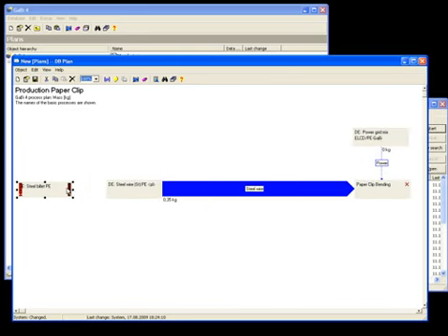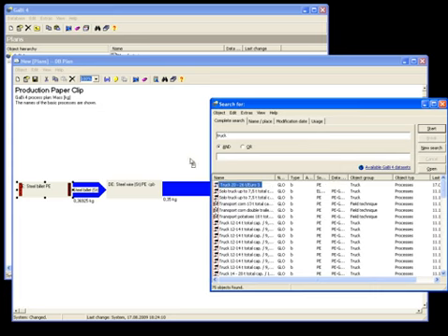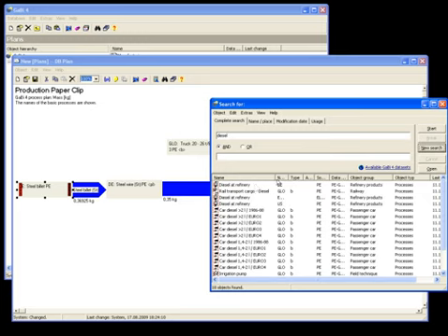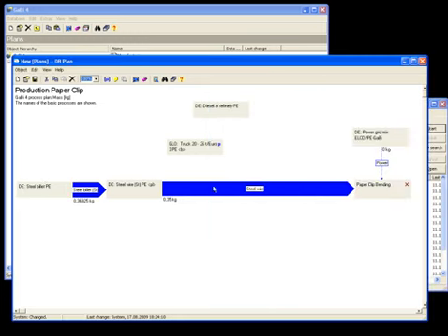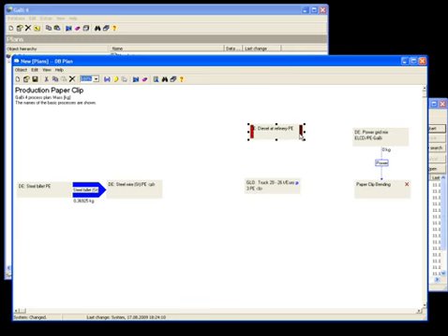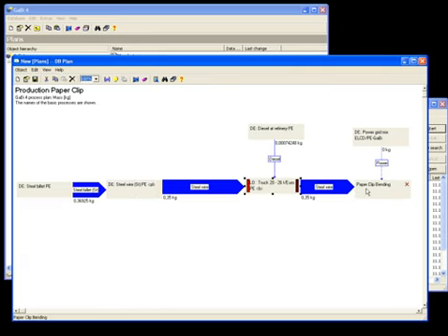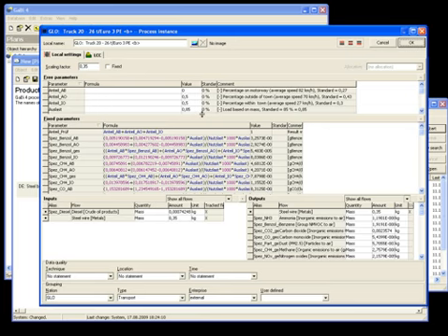Transport processes can also be added to the plan. These can be placed between other processes to represent the real-life transport procedure. By connecting processes with transport processes, GaBi recognizes that the flow from the previous process is the cargo of the transport process. There is no additional data entry needed for the integration of transport. The properties of the transport process, such as the distance, payload, and the percentage of travel on different road types, can be edited using parameters.